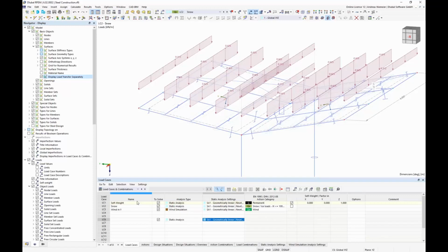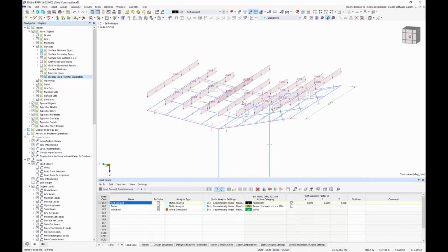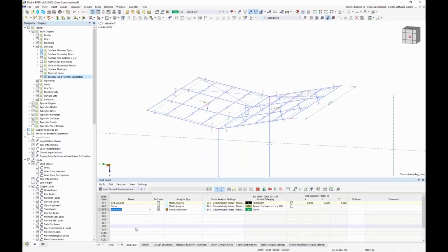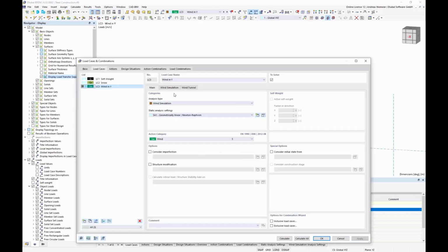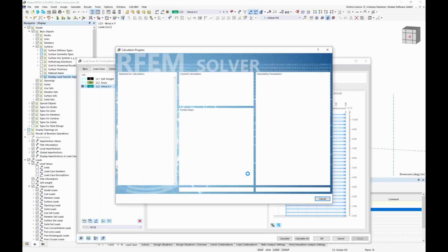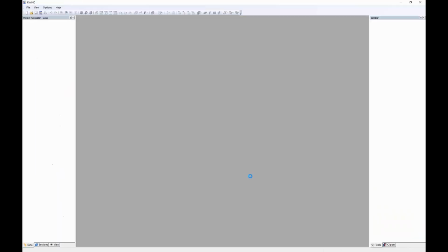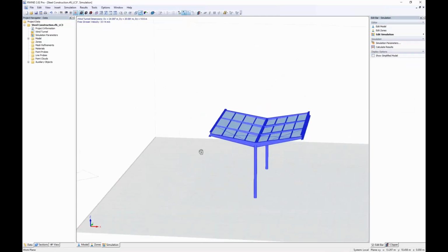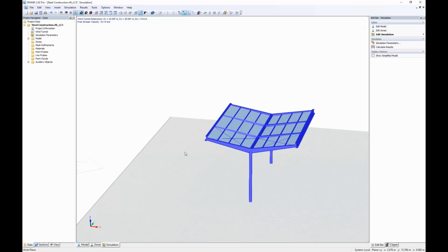And even for, let's say, self weight, you see this 1 kilogram is distributed over the surface. So the load transfer surface can act integral over all load cases. So not only for self weight and snow, but also for wind. And this is maybe the target. So you can now create wind models having these surfaces inside. If you check, you see now we have a surface inside and it looks quite good for our simulation. We have a compromise between wind model and structural model.